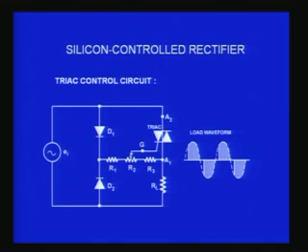So by moving this potentiometer, I will change the conduction angle here from 0 to 180 degrees. That means I can make the entire energy available at the load or no energy available at the load, but by controlling the current in the gate, that is what you should recognize, and therefore we get enormous energy saving in terms of the loss that can happen if I introduce such devices in the main circuit.